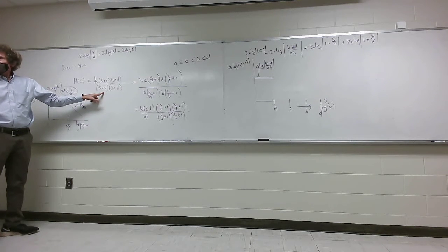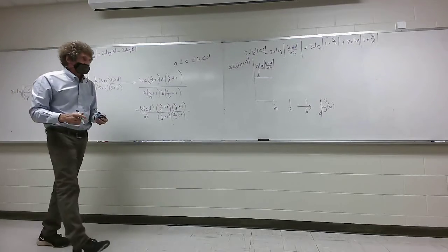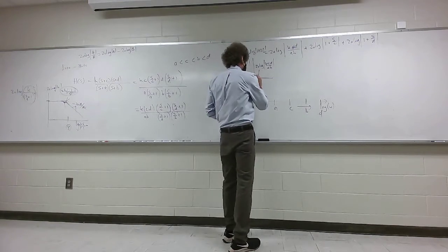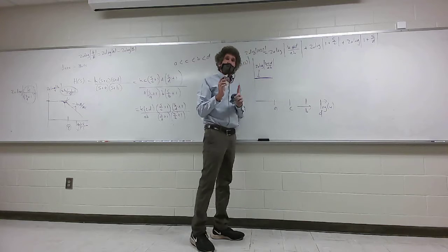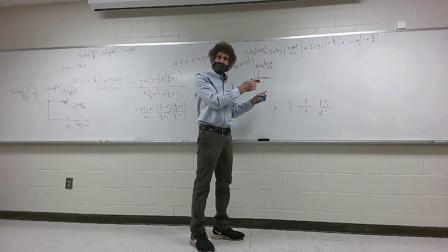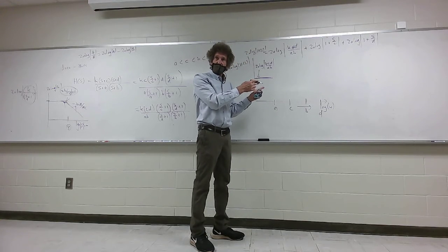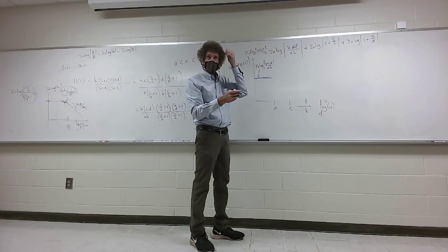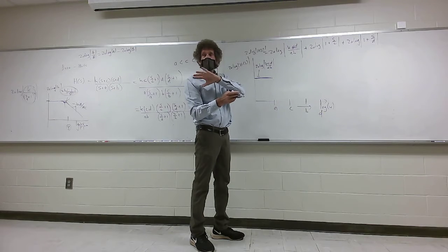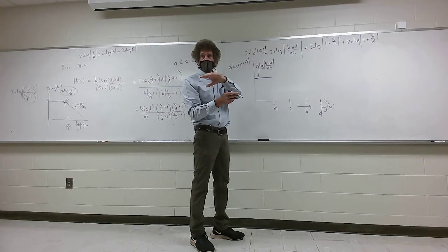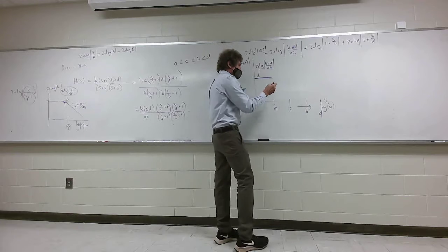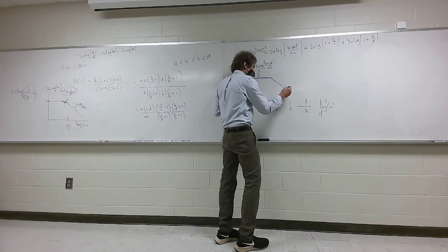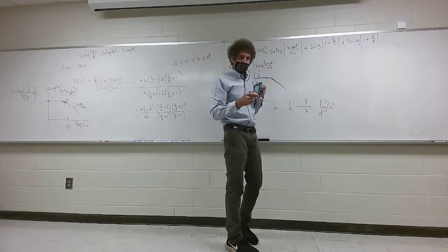Now, when you get to A in this plot, it starts going down at 20 dB per decade. Y'all with me? You just draw straight line plots to approximate this. And Dr. Hung probably does this slightly different, but this in essence is everything you need to know about a Bode plot, both plotting it and then constructing a function to represent something. So please understand this is both for synthesis and analysis. All right, now it starts going down by 20 dB per decade until I hit C. You all agree with that?